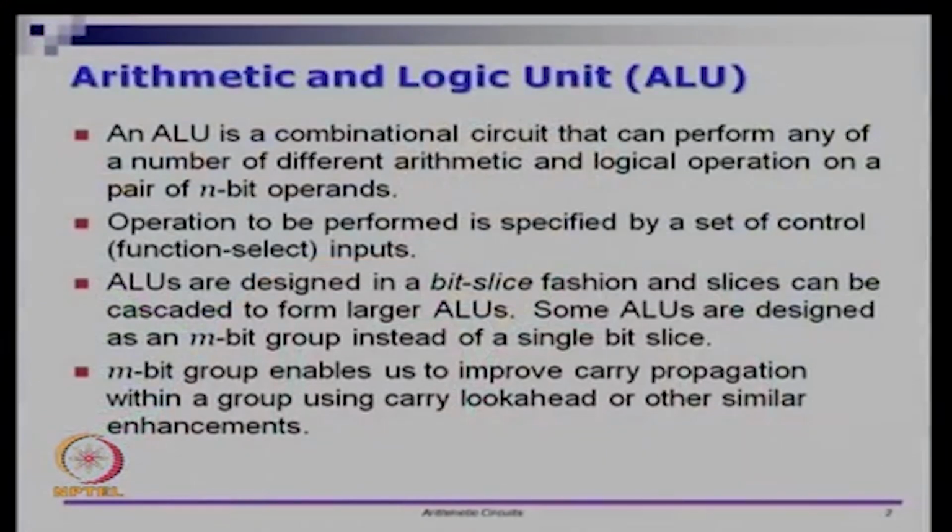If you look at any processor, it typically has what is called an arithmetic and logic unit. An arithmetic and logic unit does all kinds of arithmetic calculations. Arithmetic operations include addition, subtraction, multiplication, division, and things like comparison. You may also have logical operations like logical AND or bitwise OR, and these are all done by ALUs. The operations to be performed are usually given by a control circuit. Based on the program that you have, you may have operations which say add these two numbers, subtract these two numbers, and so on.